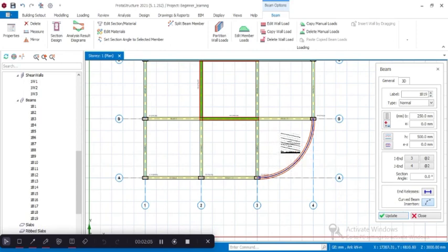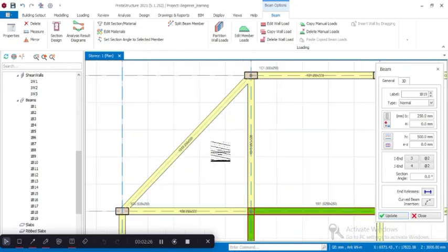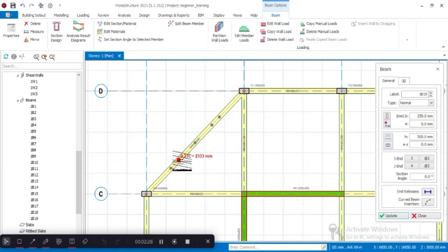So what we did was to define the radius. That's going to be minus 1500, and then we'll press enter. We created our 19 beams. Now beam creation using dynamic snap points. Let me explain what that means. When you insert beams, you have different points here. You can see the snap points: 0.25 length on the beam we've created here, 0.33 length, half 0.5, 0.67, 0.75. So each snap point represents a point on this beam.